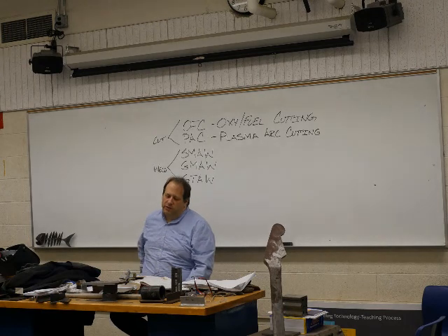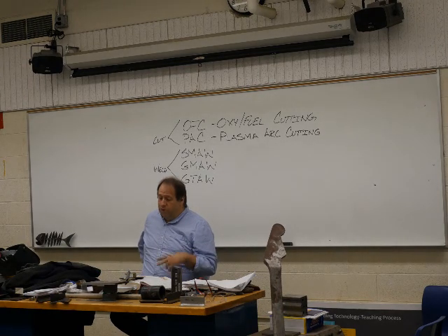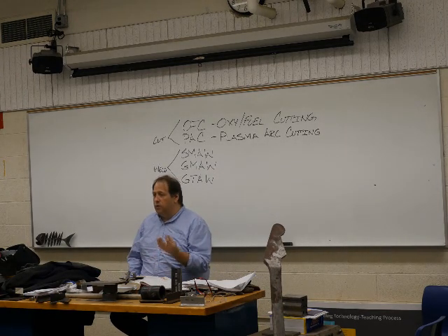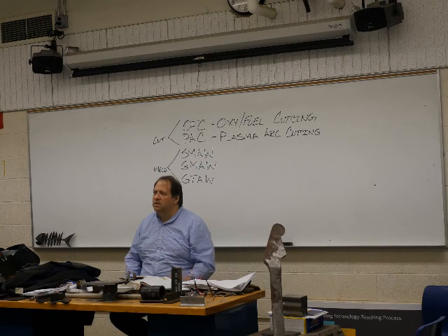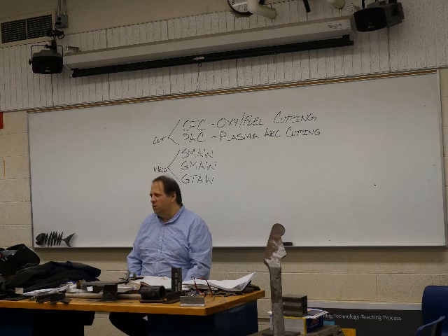So there is limitations there. So plasma cutting is just kind of the opposite. It's really good on thinner materials, but on thicker materials, it doesn't do really well. Most systems, if you were to get 1/2 to 3/4 inch thick cuts out of it, you'd be doing really well. That's about as much as you're going to get. It's pretty limited that way.